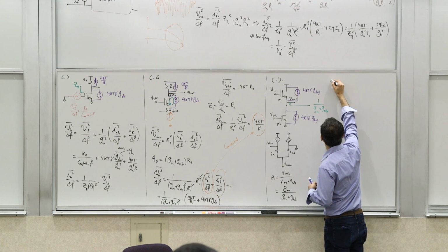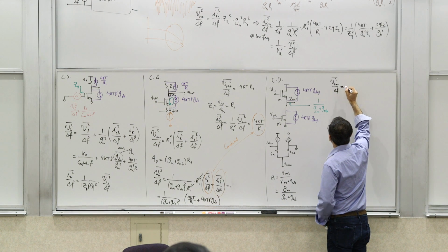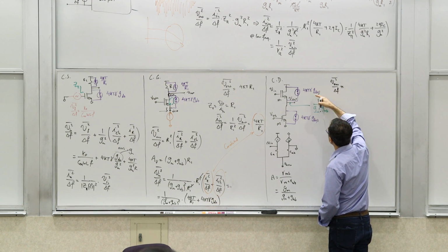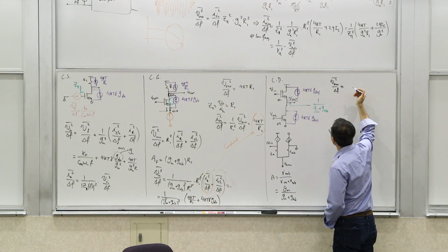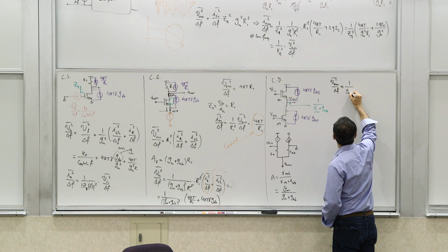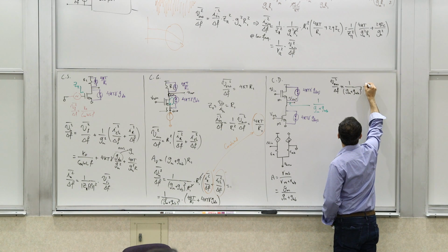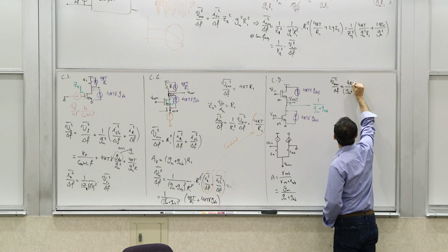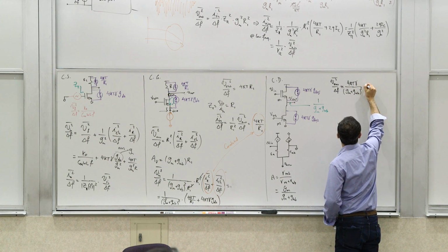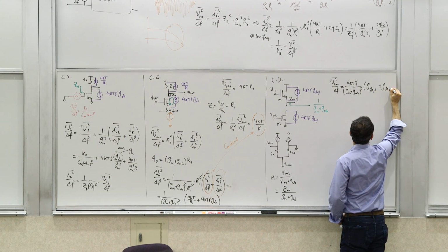So the noise at the output, Vout² over delta f, is going to be the sum of the power of these two currents times the resistance you see over there, which is basically 1 over |gm plus gmb| squared times the sum of those two. And you can factor out those common parameters, 4kTγ, assuming they have the same gamma, times gd01 plus gd02.